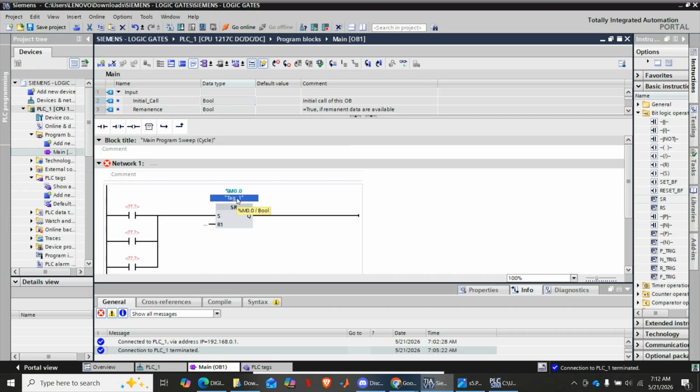Memory holds conditions temporarily. So this SR block has to hold the condition on this temporary memory, which is M, holding digital high or low. You see, there are MW and MD which hold maybe numbers, reals, integers, etc.